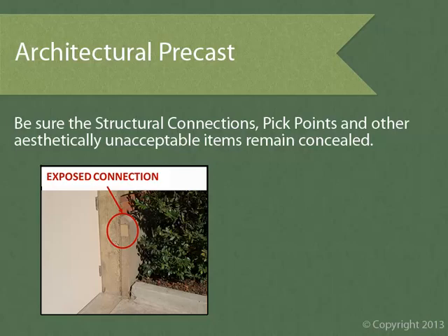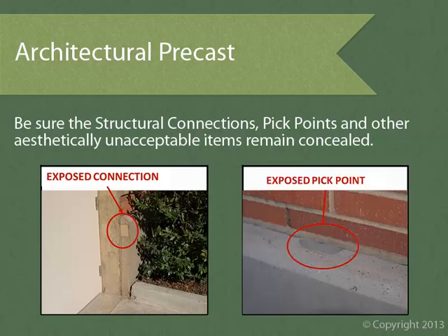This could have been avoided if it was addressed with the exterior skin coordination program. What you see in the second photo is the top of a precast wainscot panel that's about 3 feet above grade. Maneuvering precast panels around the shop, onto the trucks, and eventually into position on the building is not easy. So precast subs commonly add pick points at the tops of panels, and in this photo you see where a pick point has been patched. Having one of these patches every 4 feet or so around the building is not attractive.